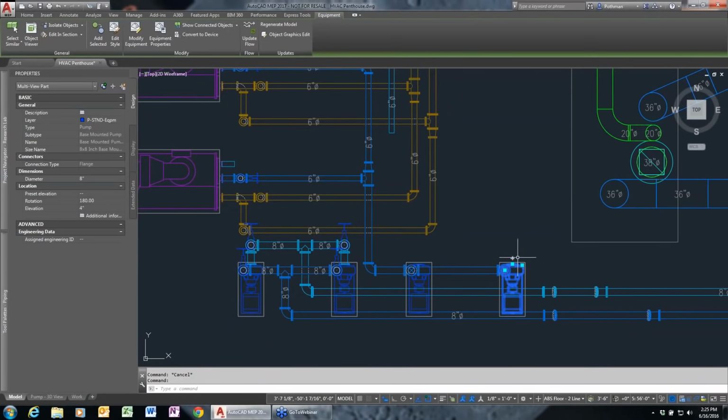Kind of the difference between a pipe and a plumbing line in AutoCAD MEP is a pipe actually will be modeled in 3D with 3D geometry and 3D space. The plumbing line is really more of a schematic representation. So often when people are doing plumbing layouts, especially in the past, today people are actually starting to model pipe plumbing, you can just use a schematic plumbing line instead.